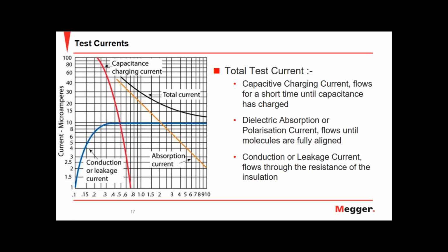And once you do the measurement, and once the capacitive current has died down and the specimen is charged, the value that you would get would be based upon the leakage current or the conduction current, and that value should be constant for the remainder of the life of the insulation. And if the insulation deteriorates, then obviously the value would change. But a higher length of the cable would affect the capacitive current.